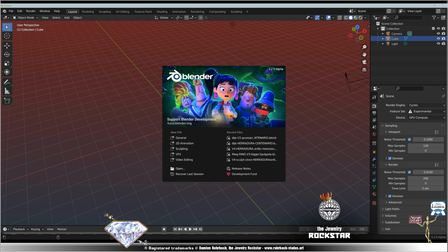Okay, here, instead of using the clipping, you go to edit mode. So I'm not using the clipping, but I'm going to use the merge at a distance of maybe 0.2. And you can see that now the solid is closing here at the top and also at the bottom.